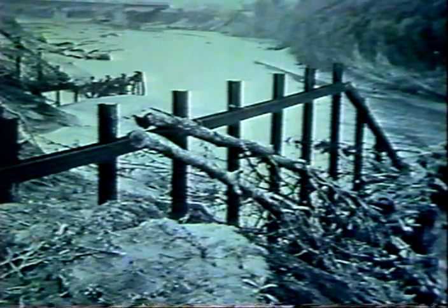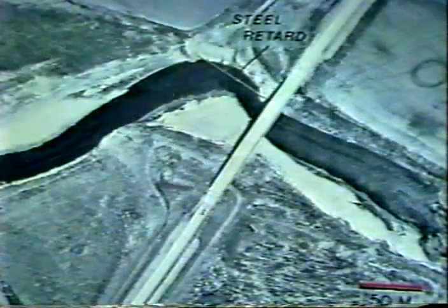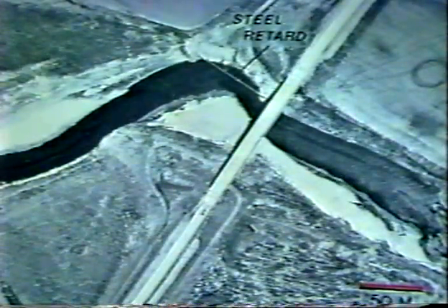Permeable spurs, such as these on the Grand River in Missouri, do not require the use of riprap and have proved effective for bank protection and control of flow alignment. It is important that the facing of the spur be in contact with the stream bed. Retards like this one on the Nishnabotna River in Iowa are suitable for control of flow alignment at sharp bends near a bridge.